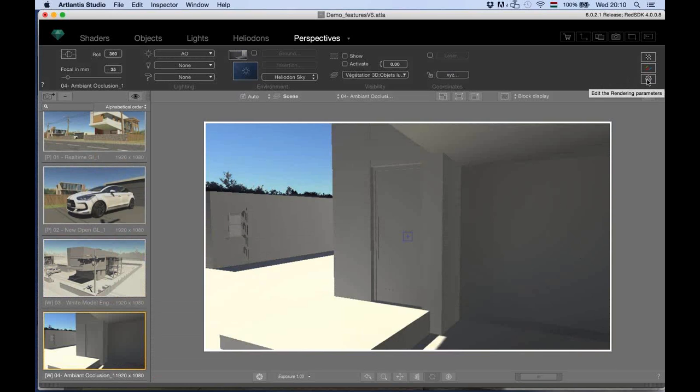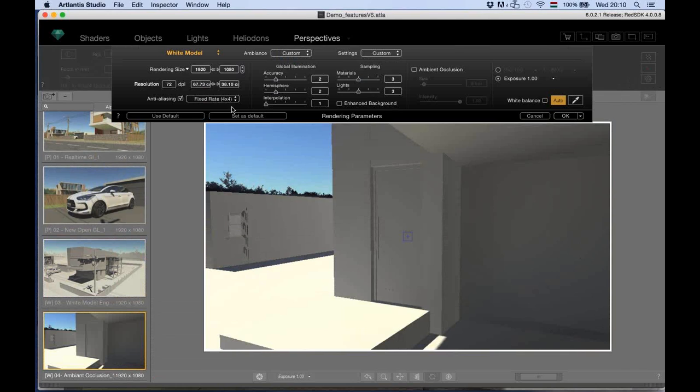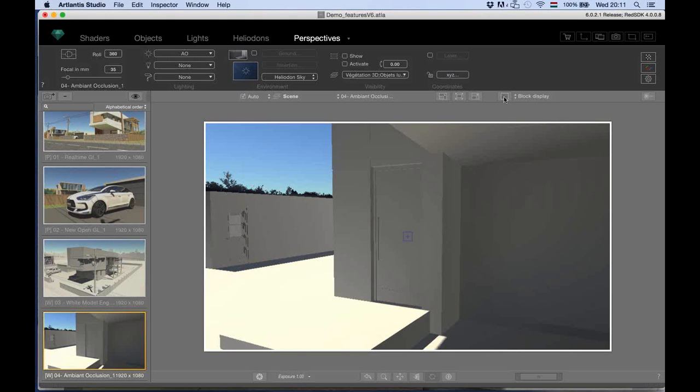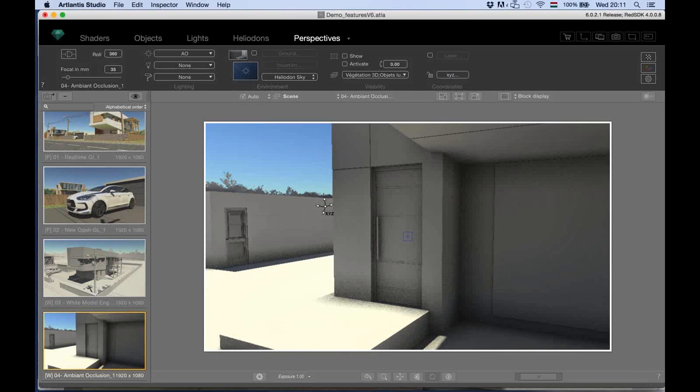This can be set in the rendering parameters. I reopen it. You see, we spoke about these 5 parameters for the engine. The rest are additional features, possibilities, and here is the ambient occlusion, which is one click. I activate it. I can set the size in centimeters. I can set the intensity, okay, and I need to ask for a refreshment of the preview, because this ambient occlusion, this virtual shadow will be applied as an extra filter at the end after the refreshment was done.